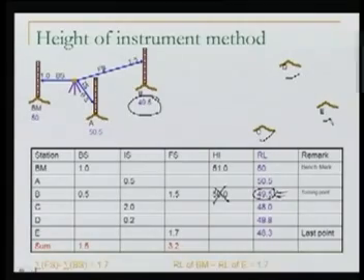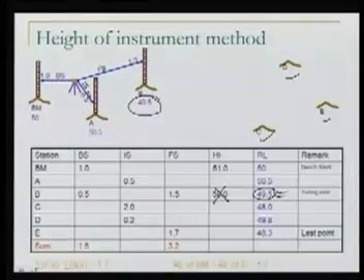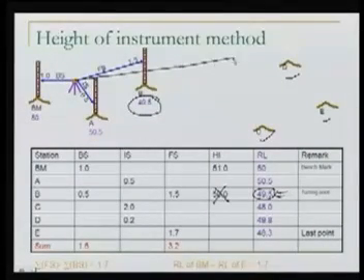So here you have to take a decision. The decision is, should we continue from the same level position where the level is? Should we do that or should we shift our level now? Because if I continue from the same level position in this case, as you will see now in the slide, if I still continue taking the observations from the same level position, my back sight and foresights will not be balanced. My foresight is going to be very, very long. So this is not desirable.